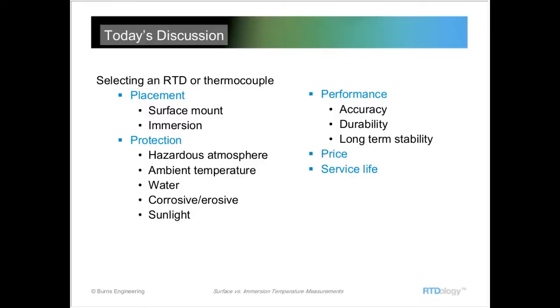All right, thanks, Jeff. Well, today I wanted to address the difference between surface and immersion measurements. It's a question that I get quite frequently, and I wanted to throw out some of the pros and cons of using a surface mount RTD or thermocouple versus something that's immersed directly into the process. So we're going to look at surface and immersion and how they are placed in the process, and then how we protect them, and then we'll end up looking at performance and finally price, and then what we can expect as a service life.